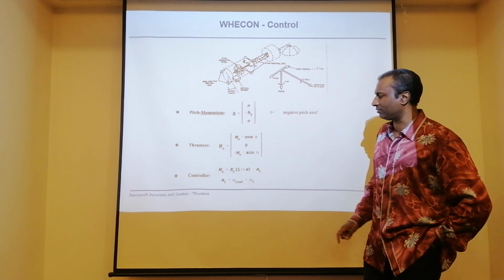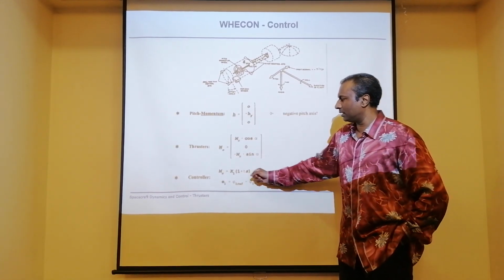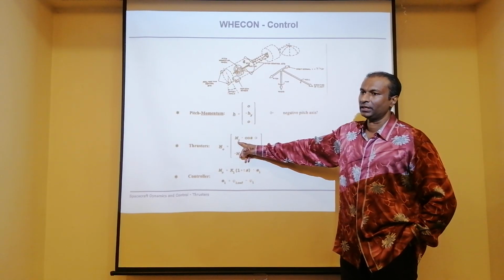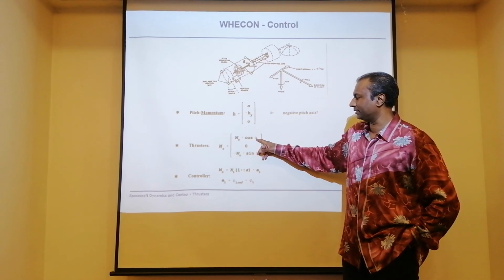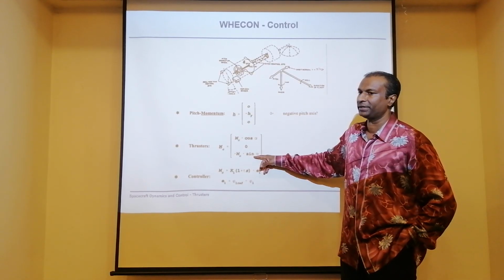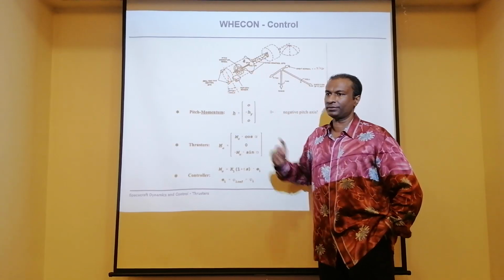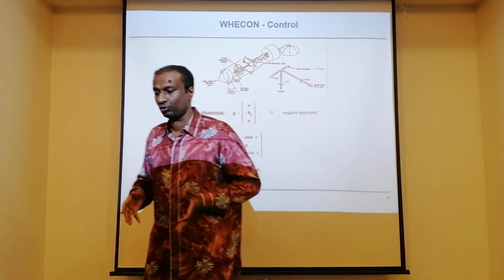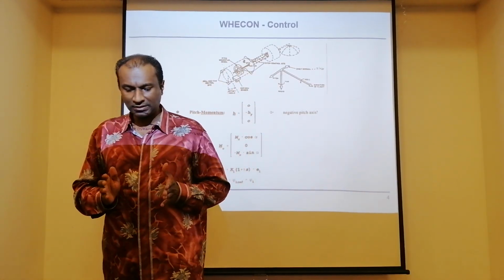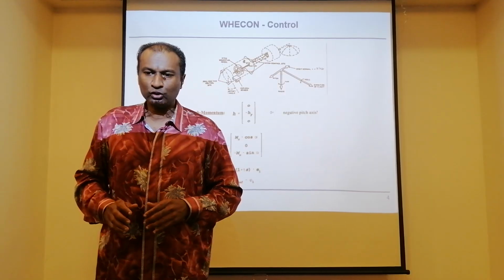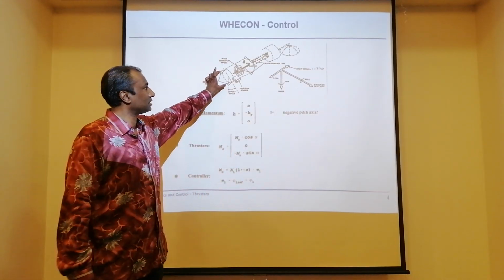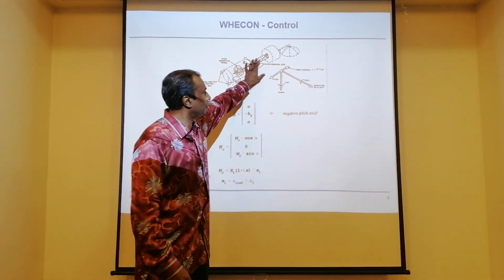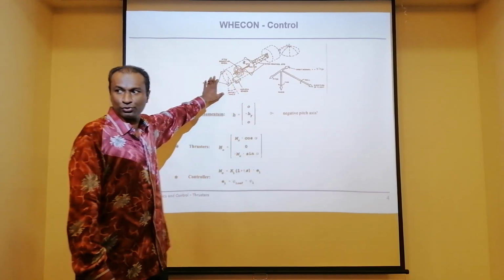The only thing I've introduced today is this thruster torque. Basically, I can say that the thruster torque would be the cosine angle or sine angle of that particular configuration. Now, why this design? Remember, the thrusters can also be used for translational motion. So there is a design consideration that these thrusters can be used not only for attitude but also for translational motion.